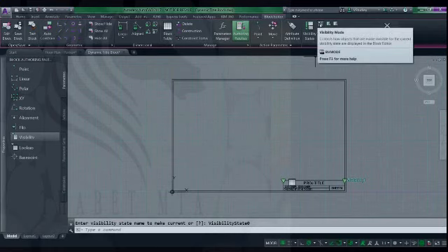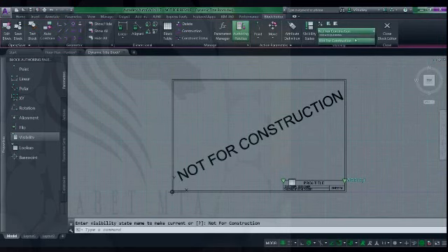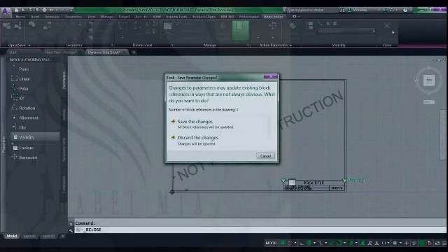Here I'll show you what the visibility mode does. You can change this with the command BV mode, but you can also use the little toggle up here in the ribbon. So BV mode. See, it just grays it out, and then if I switch between them, I can still see what's invisible. It's just grayed out there. So I'm going to close the block editor, show you how this works, and then we'll wrap up.